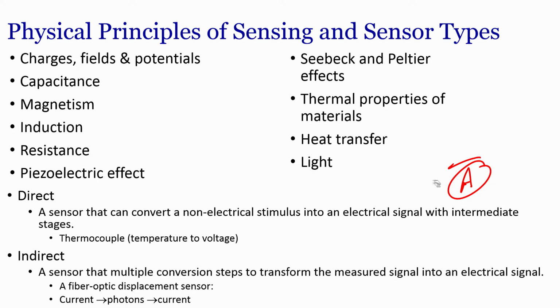The same way you can understand the piezoelectric effect. There is a difference between piezoresistive and piezoelectric. Piezoresistive is when we apply a pressure, there is a change in resistance. Piezoelectric is when you apply a pressure, there is a change in voltage, right. Piezoelectric crystals exist. Piezoresistive materials can be designed by doping polysilicon with boron, so we can design a piezoresistor.